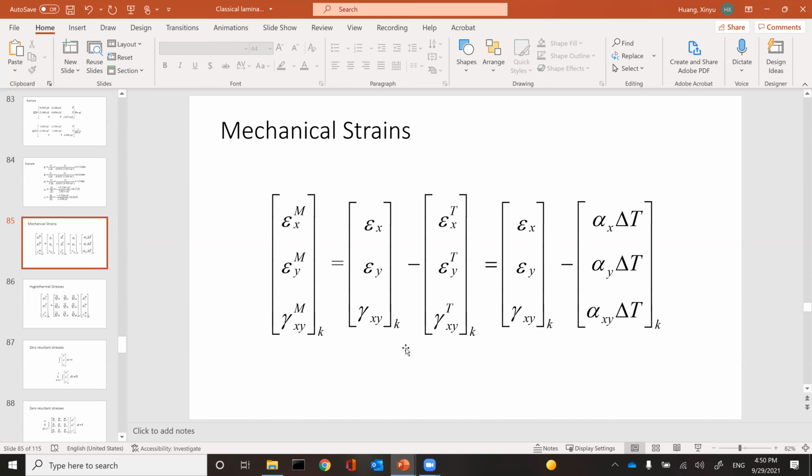So when you take the laminate out of the autoclave, there's already stress in there. The layers already start fighting. But an interesting factor is, since you have no external load, all the internal stress is actually self-balanced. They fight, but they somehow balance out.